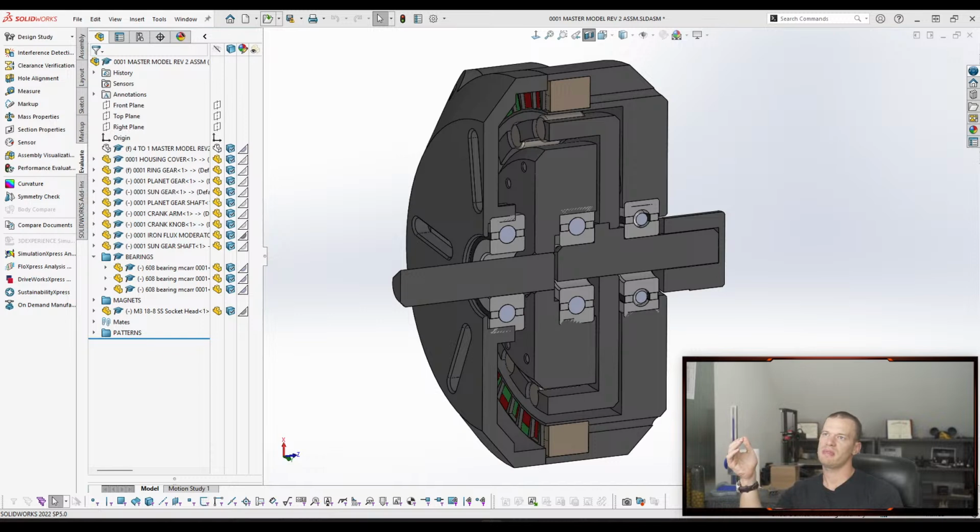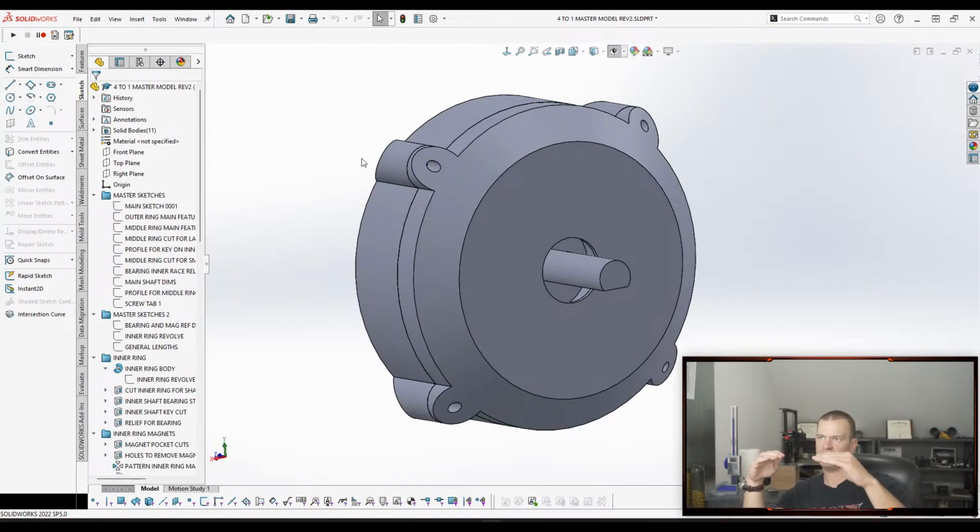I think the only reason I would prefer skeleton sketch is because the thing that you're sharing is more lightweight. And I don't know if that's a good thing or a bad thing. It probably depends on what the design is and what the context of the project is. But to me, you're doing a lot of your design work in a single part file, which is the thing that everybody has to access, say each engineer has a different part in your subassembly.